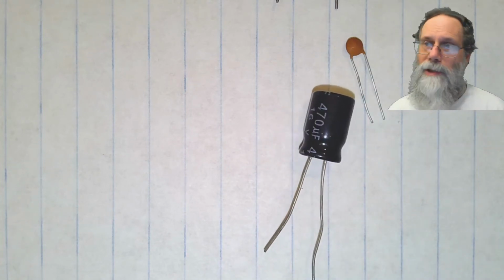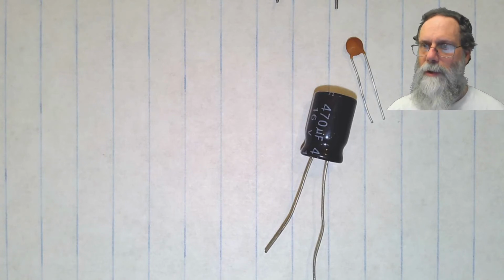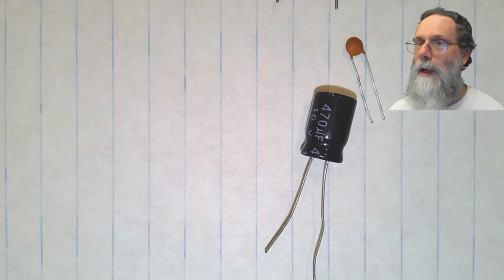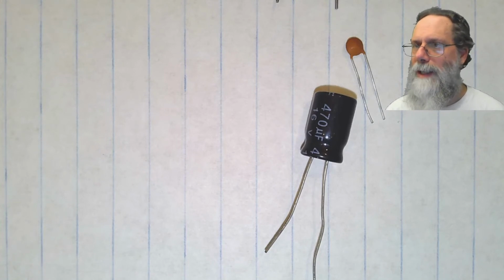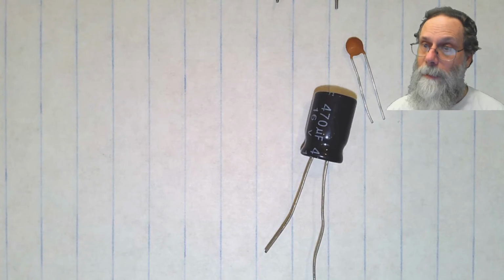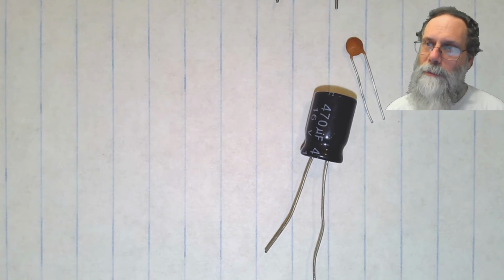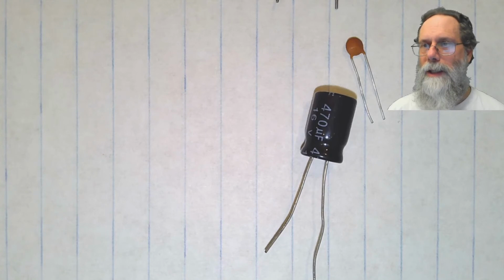Now, the electrolytic capacitors work on a rather different way of creating the insulator. Rather than having a separate material for the insulator, like the ceramic or the plastic that's sandwiched between 2 metal plates, what electrolytic capacitors do is to have the metal plates and to grow on one of the metal plates a very, very thin layer of oxide. The oxide's an insulator. The metal plate is usually aluminum, sometimes tantalum if you've got a lot of money. So usually it's an aluminum plate with a very thin layer of aluminum oxide on it.